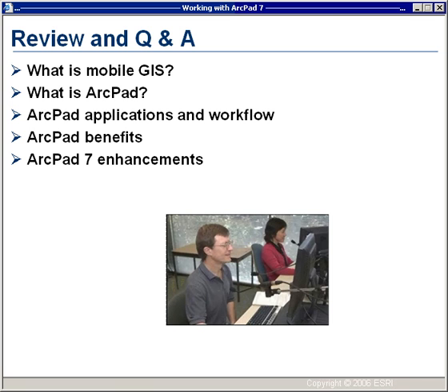The easiest way to determine whether you've reached this limitation or not is to use the tools in ArcGIS Desktop to export the current viewed image to a TIFF image and view the size of that TIFF image. If it is over about 17 megabytes, it is too big.